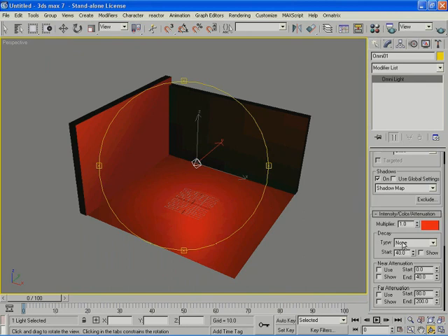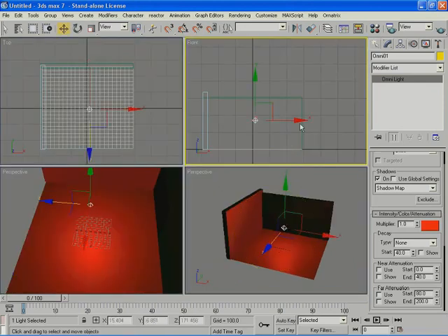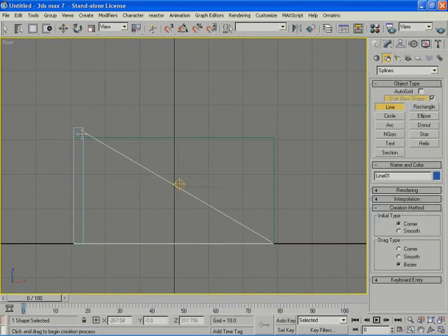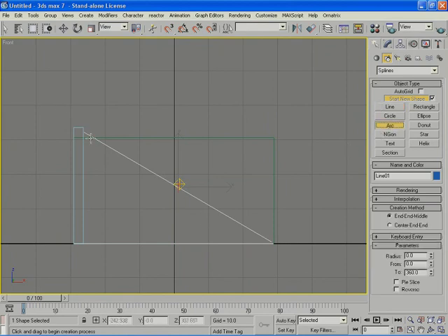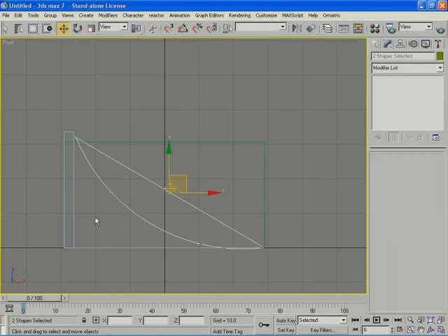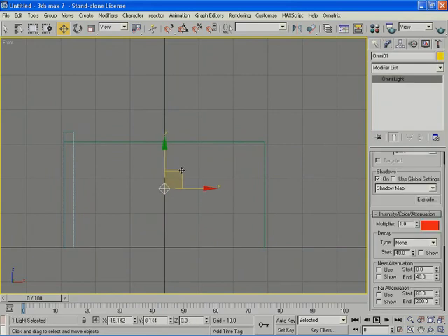Now it can decrease in 2 ways. It can decrease according to a straight line, like this. So this is the highest intensity, and with distance it's going to decrease in a straight line, or it can decrease in an exponential line like this. So the further you go away, the less and less light intensity you're going to have, but at this area you're going to have the highest intensity. So it's not linear as it is over here. So this is called an inverse square decay type, and this is called a linear decay type. So you don't have to worry about this, but know that real lights decay using an inverse square equation.